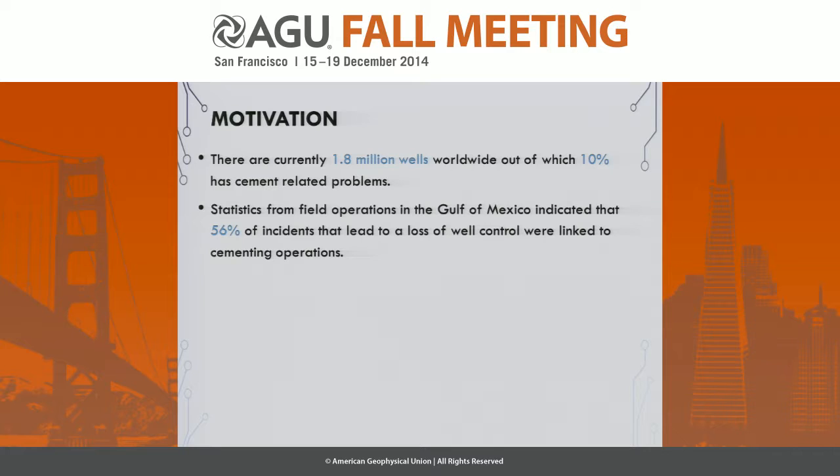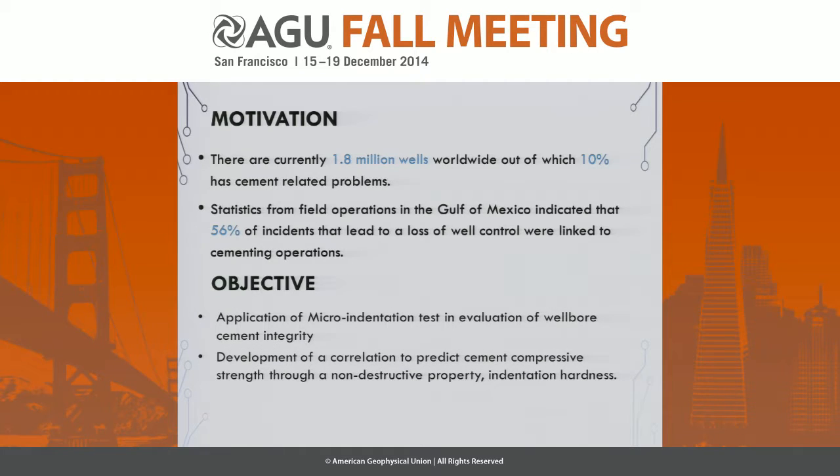The objective of our research is to apply the micro-indentation test in evaluation of the well-bore cement integrity. Also, we are hoping to develop a correlation to predict the cement compressive strength through a non-destructive property, the indentation hardness.